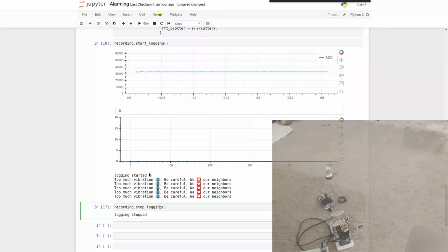But once I have the thresholds, I can code it in C on the Nucleo board, and instead of printing a message, send a notification via Bluetooth to a Python script running on the desktop, and then send a notification to my cell phone via a Telegram bot or something.